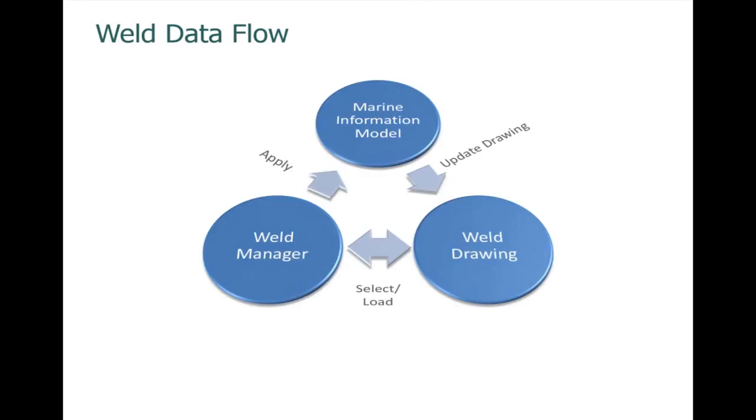Before we go into looking at them a little bit further, I want to give you a little bit of background on how they work so that you'll understand better how I'm working with these two objects in the demonstration. In traditional ShipConstructor projects, you create your parts in model drawings, you save those model drawings back to the marine information model, and then you generally create views of that marine information model of those parts, typically in production drawings or reports, possibly now through Publisher LT and so forth.